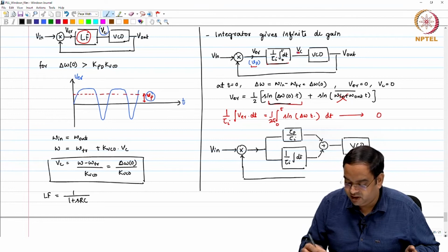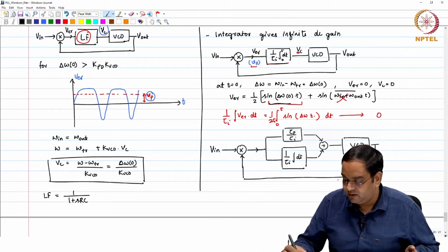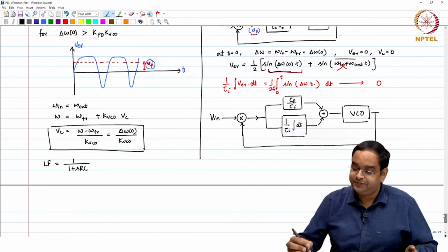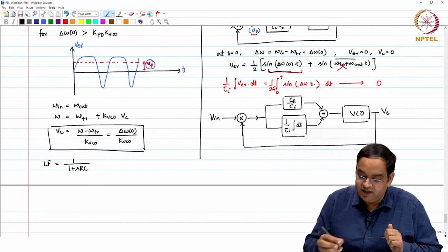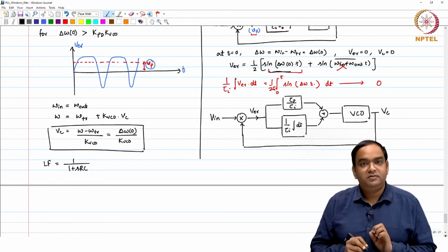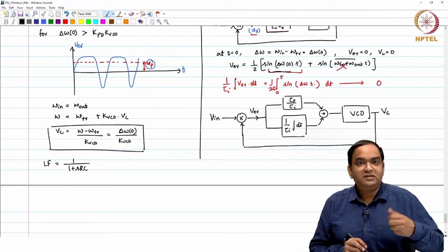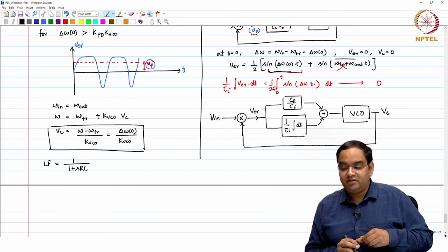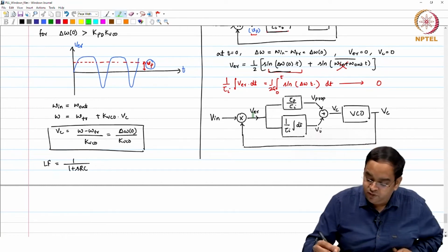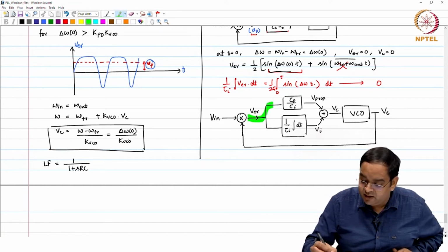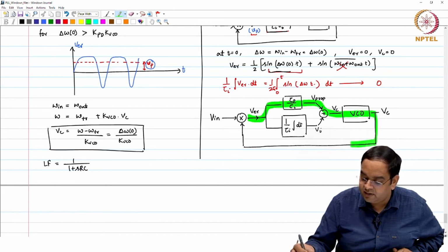Okay. Now, just try to understand it a little intuitively. You start this PLL with frequency error delta omega 0, you get V error, right. This is, by the way, V control, this I will call Vi and this is V proportional, because there is a path from V error through tau p by tau I going to the VCO and coming back.